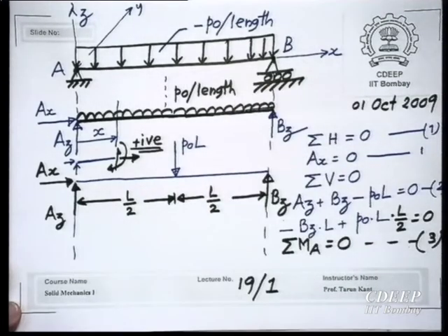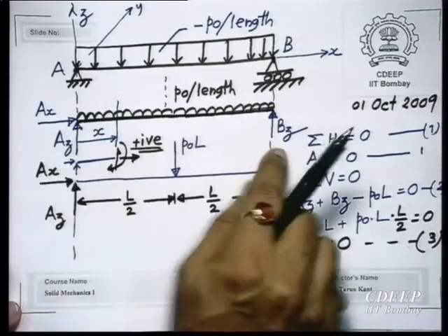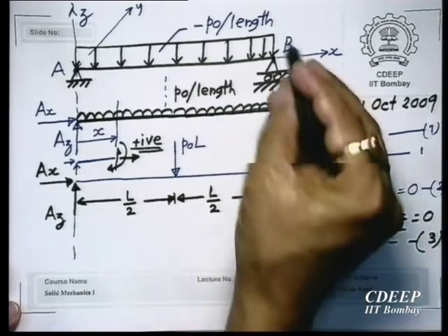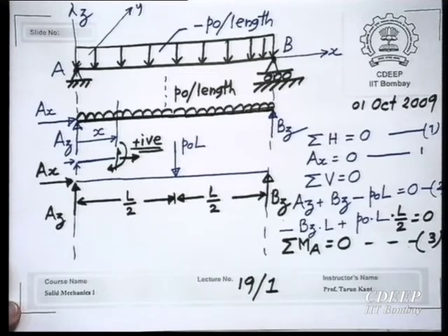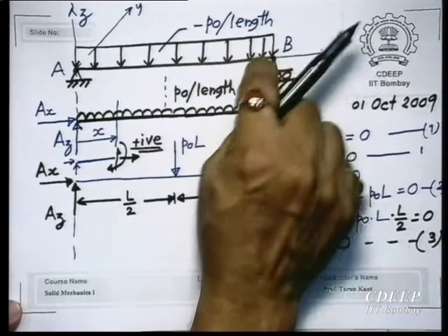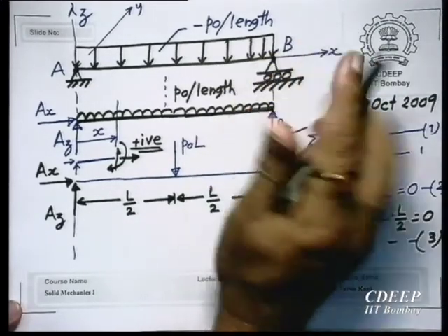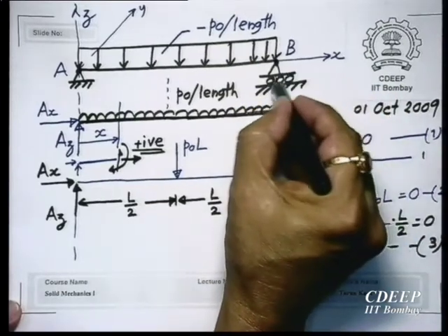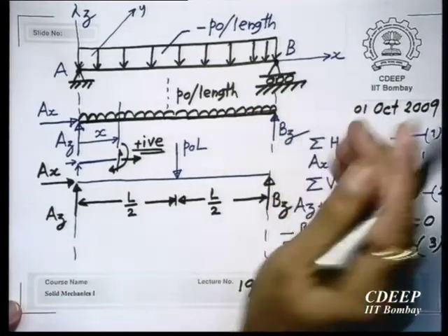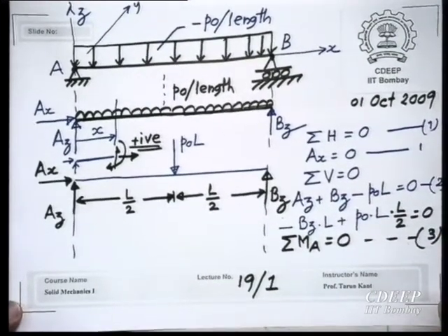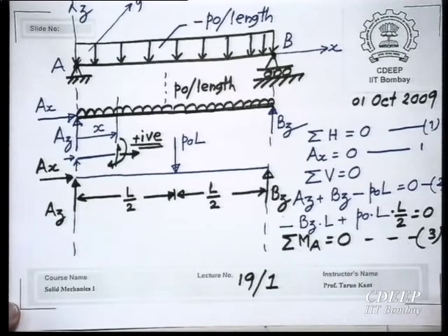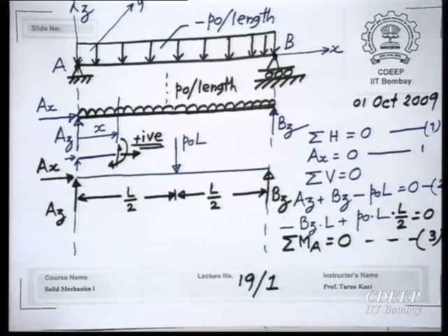This is the free body diagram, the second one is the free body diagram. There are two reactions here, one reaction over here. This one, a roller also is shown like this, the way I have shown here. Either you show only a simple roller, round, or first you show a hinge and put the hinge on a roller. So, that means this x direction movement is allowed. So, this is all right.